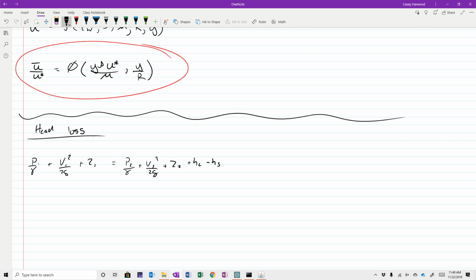In pipe lab number 3, did the TAs have you guys feel the pipes after about 20 minutes of running? If you had started out the lab and felt the pipe, it would have been cold, room temperature. After about 20 minutes, those pipes are nice and toasty hot, just from the frictional resistance of the air flowing through them. And you can feel that the rough pipe is hotter, reflecting there's more energy being lost to that thermal element.